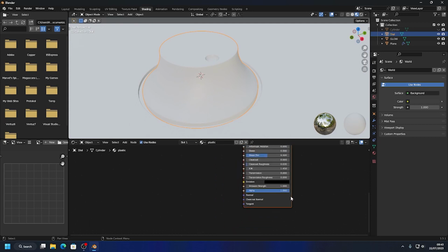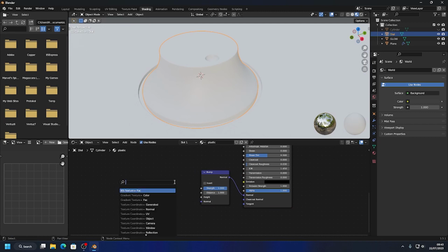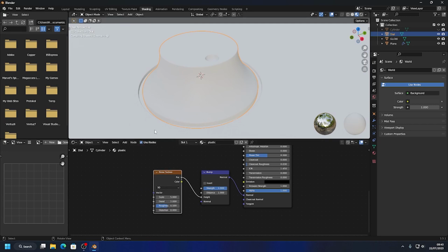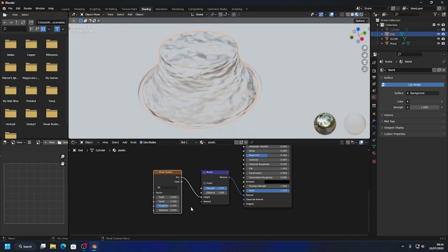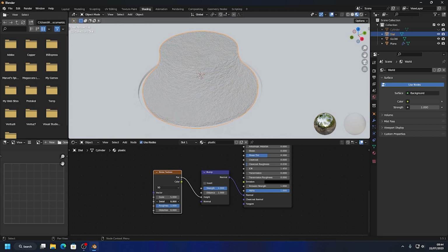And what we'll do is go to normals, drag off this for bump map, a bump, and then from the bump, I want to add a height, and I'll say noise. I want to add a noise texture. There we go. Then it will go crazy. There you go. It looks horrible, right? Increase that roughness, increase the detail, and the scale. You're going to just drag this in. So we've got loads of bump, and now I'm bringing the strength down, so it's really small.